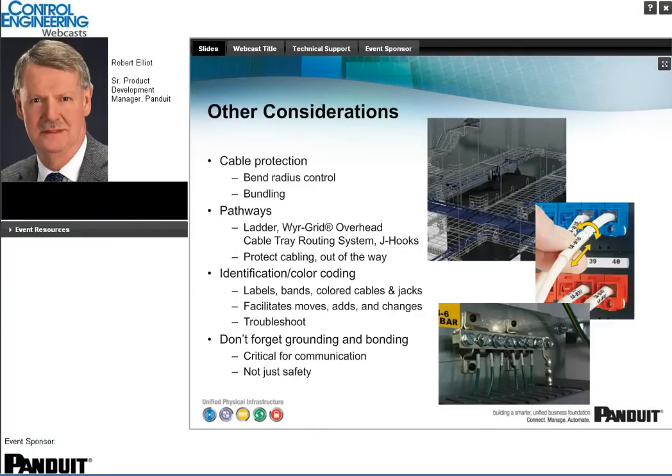Labeling, the use of color coding to assist labeling and infrastructure identification. Labels, bands, colored cables and jacks can always be used to facilitate that. And finally, don't forget grounding and bonding. It's critical not only for communications, but also safety, of course. So these are just some of the considerations here, and I'd like to just hand it back to Mike for just a brief wrap-up.